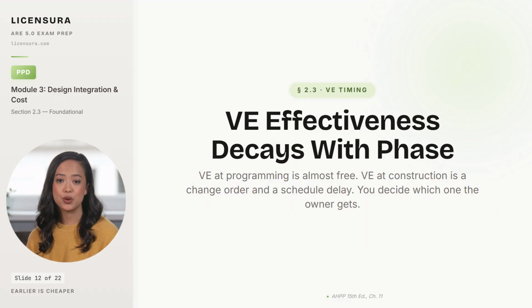Here is the VE timing rule the exam will hand you in a scenario question. VE effectiveness decays as the design progresses, and the cost to implement VE changes climbs in the opposite direction. VE at programming is almost free, because the team is still trading ideas on paper and no commitments have been made. VE at construction documents is a redesign event. Drawings get reissued, specs get rewritten, consultants bill, and the schedule slips. VE during construction is a contractor-initiated value engineering change proposal, or VECP, which can save money but typically comes with delay claims and warranty disputes attached.